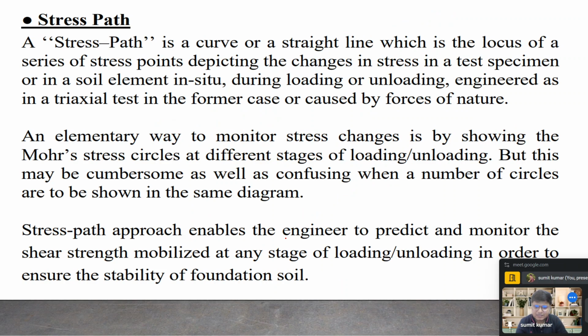So we are able to depict the interrelation in a good manner, and that's the only thing I want to state. An elementary way to monitor the stress changes is by showing the Mohr stress circle at different stages of loading and unloading, but this may be cumbersome as well as confusing when a number of circles are shown in the same diagram. The stress path approach enables designers, engineers and professionals to predict and monitor the shear strength mobilized at any stage of loading and unloading in order to ensure the stability of the foundation soil.